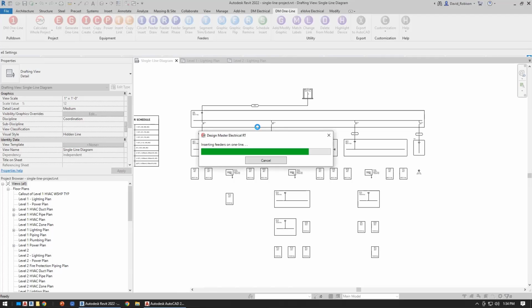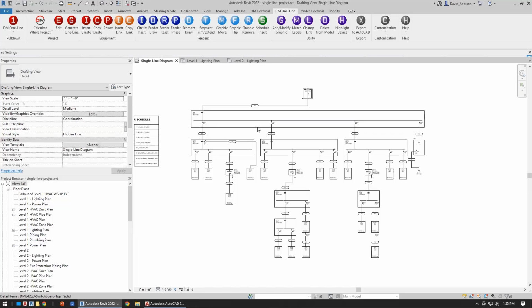The one place where you would do it is when you're doing something like we're doing, where you're getting your customization set up. So you'll run the generate and say, oh, that didn't generate how I want it to. Make some changes to your customization. And then you could erase it, run the generate again and say, okay, now it's coming in right. Once your customization is set, in future projects, you shouldn't have to adjust them because they're set. And then the generate command will come out with as good as it's going to get, and then you work from there. The idea is that you make your changes, you move things around, but you don't keep running the generate because then all those changes you've made are going to get lost.